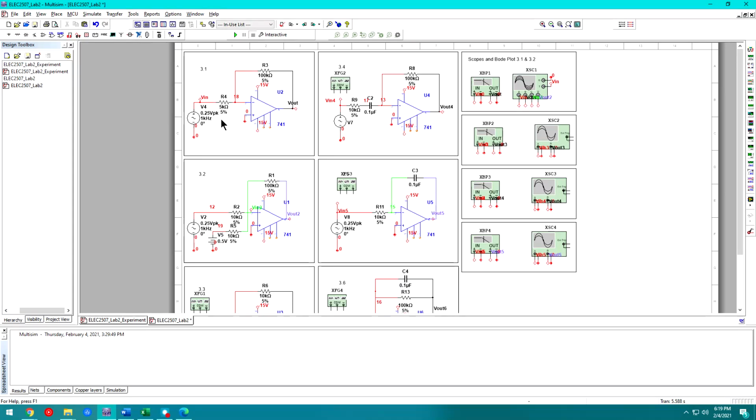So you can go ahead and calculate those and see what they'll be, because the gain that you get out of this circuit has to be within those bounds, right? It has to be within the plus or minus 5% tolerances, and therefore by doing those calculations you'll find a range which your gain could be within.